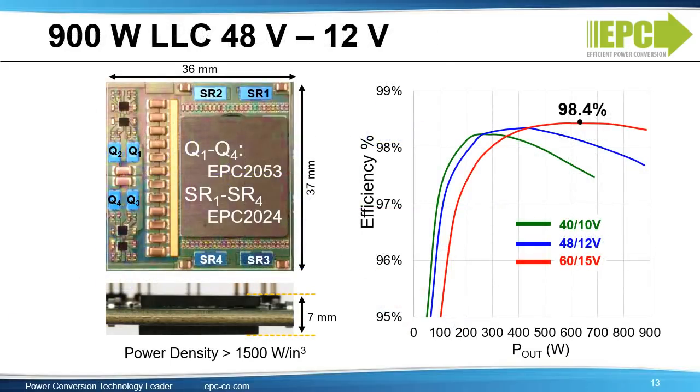The LLC is the best solution for over 600 watts and achieves 98% efficiency. Switch capacitors have limitations above 600 watts. Buck converters can deliver a kilowatt or more, but the efficiency is generally lower, around 97%, and a big inductor and a big heat sink are required.